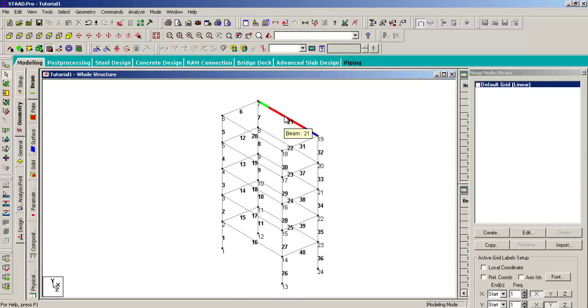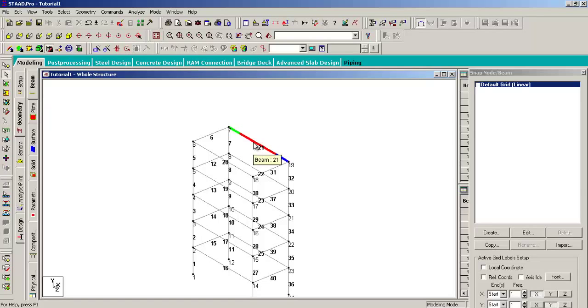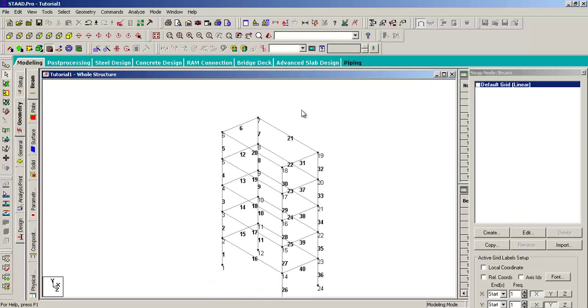So like I had told you, if we hover over any beam, we have 3 colors and the distance is calculated from the green part or the green end of the beam. I want to add some midpoints in these beams which are parallel to z-axis, like 21, 20, 19, so that we have a square structure, square slabs on the roofs and floors.